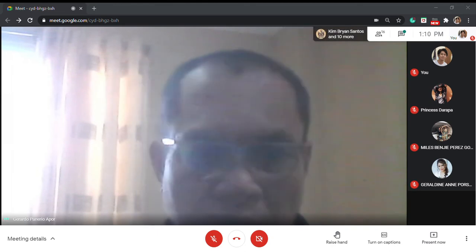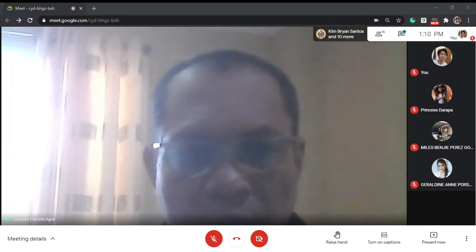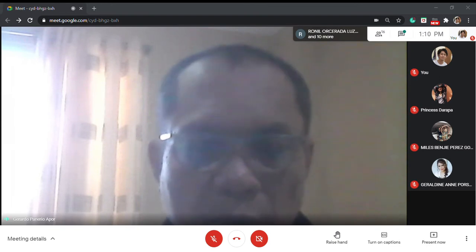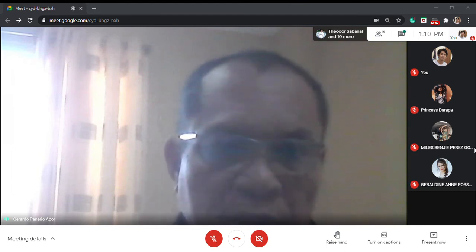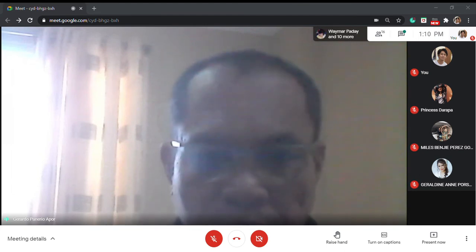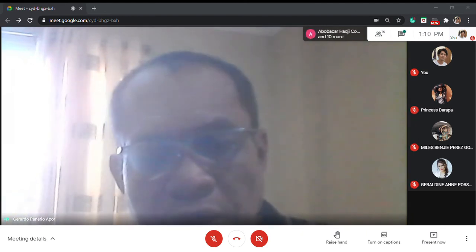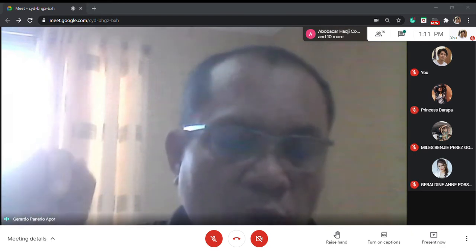So that means you are going to sum all the virtual work of the whole length. That's why we have M1, M2, M3, and big M is for the moment expression for the real load, and small letter m is the moment expression for the virtual load.